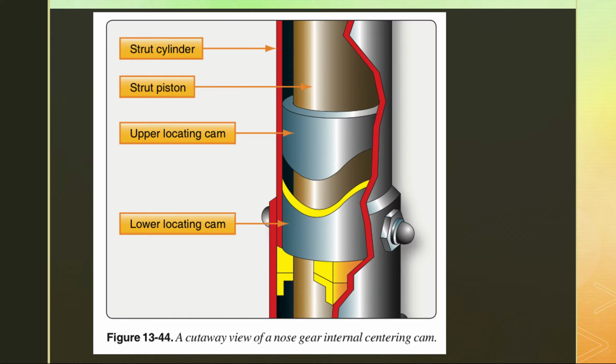Now, it's really important with retractable landing gear, nose wheel specifically, because usually the mains don't turn, usually, because there's applications where they do, but usually it's the nose wheel that turns in these tricycle gear aircraft, and you want to make sure that it retracts, that it's straight when it retracts. The recesses these landing gear go into generally aren't that much bigger than the tire, so it's really important it comes up straight. And one way of doing that is by having a centering cam inside of it.